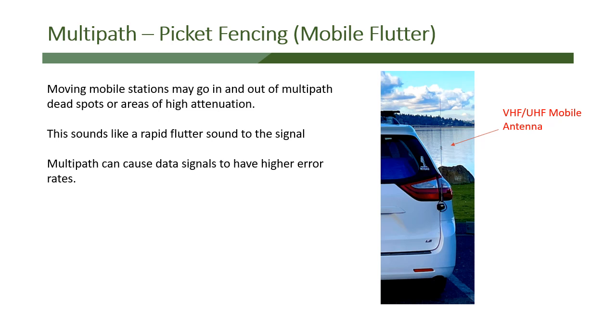So another aspect is when you're operating a station mobile. So you can see on the right, there's the antenna at the back of my car. It's a dual band VHF UHF mobile antenna. When I'm around the city driving normally, the antenna is mounted, as you can see, at the back of my car. Not the best place with that big body of metal sitting there. However, if I'm doing a long distance trip, I have another mount at the top of the car, which then gives me more range because at the top of the car the metal is now acting in a different way. It doesn't interfere in the same way. And so therefore I get better range when I'm in a situation where I don't have to worry about the height of the car and the antenna.